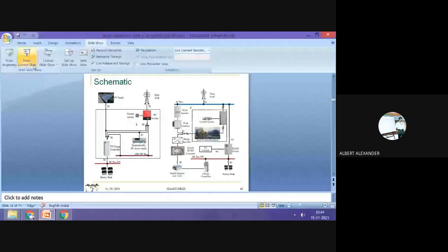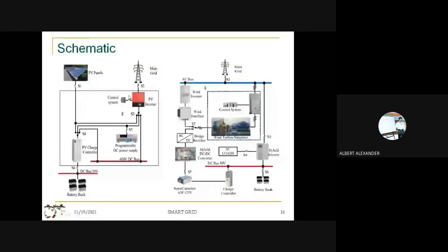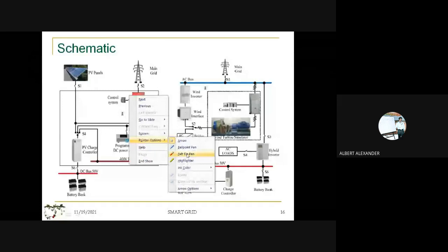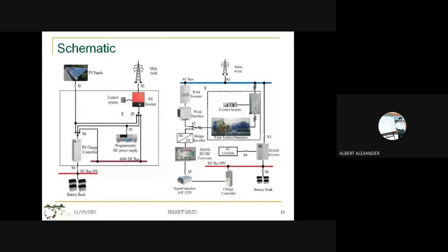But for grid connected systems, we also want my direction to be bidirectional. That is, from the battery I want to connect this inverter to convert my DC to AC, and then the AC is given to the grid. For example, when the demand is more, I want to get the power from the grid. Power from the grid means I'm getting AC power from the grid. So now the inverter should act as a rectifier. When the direction is reversed, this inverter should act as a rectifier, and then it converts the AC power from the grid to DC, and that DC I can store in the battery.